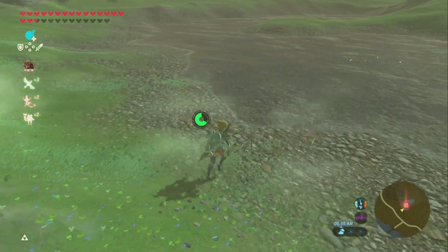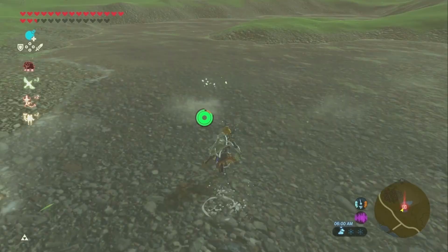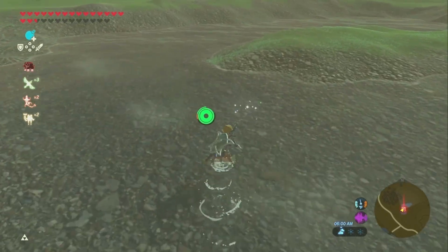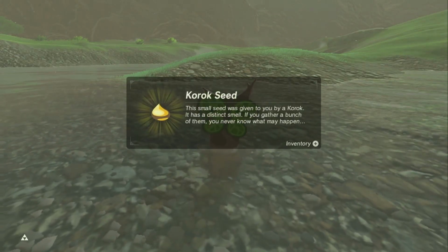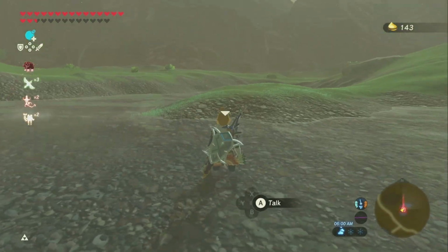Low water pressure and flow. Causes: sludge buildup. Implications: functional issue. Strategy: flush the system. Low water pressure and flow.